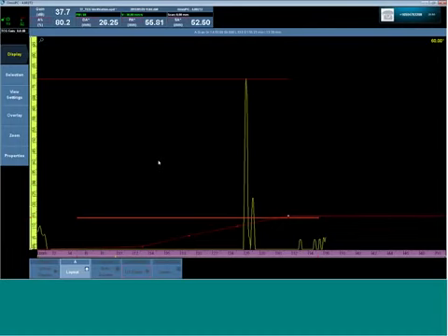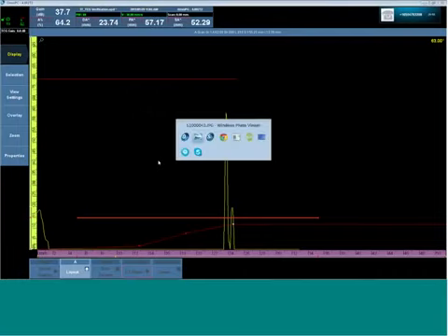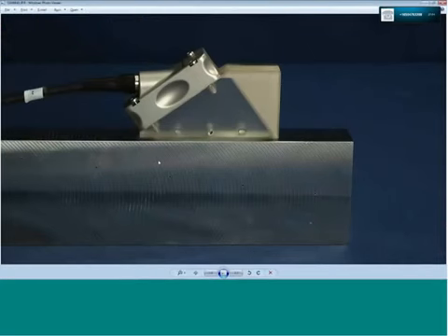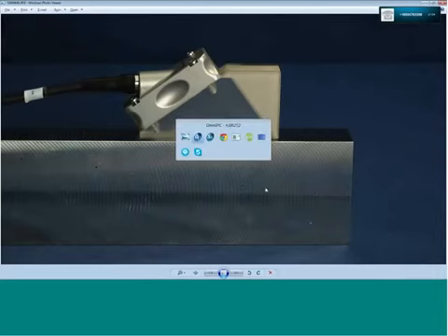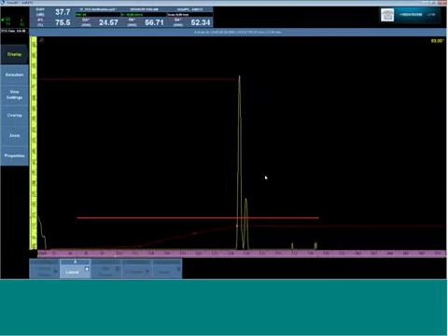So we can see right away from one single phased array probe, like we're seeing here, looking at a regular calibration block, we can change the angle, the beam shape, the focal point, and many parameters of this A-scan that were previously related to hardware.